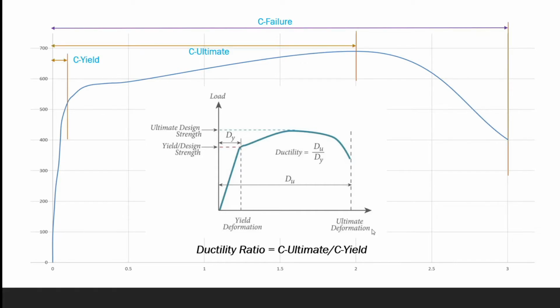This could be calculated for the failure point, or at the ultimate point compared to the yield point. These ratios are very important indicators of the cross section's status as well as its ultimate capacity to deform or to resist the moment without completely giving way.